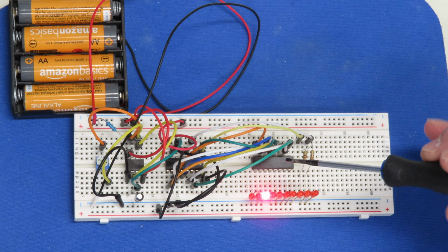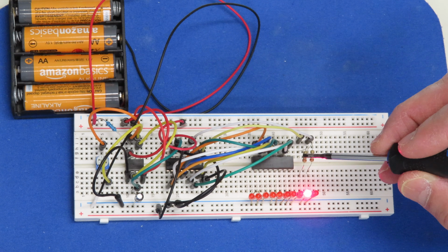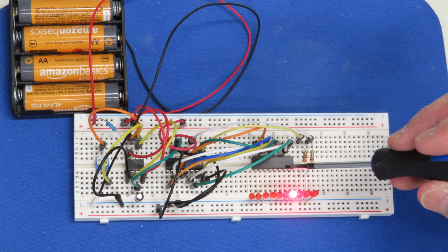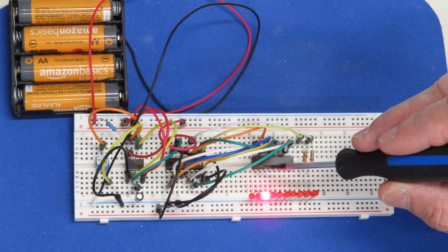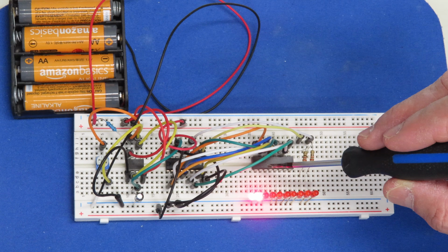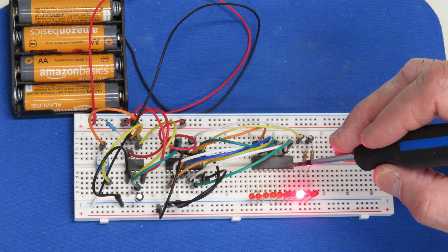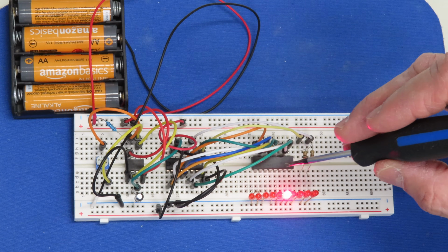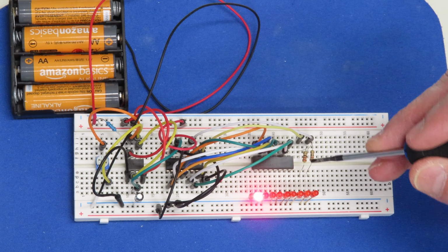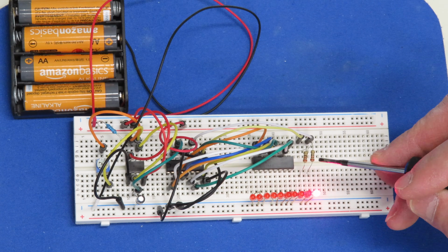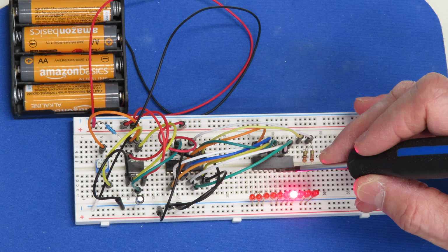This is not an integrated circuit. This is what's called a resistor array, and all it is is a series of resistors. Now, this is a 16-pin array, and it has 8 resistors in it, so it's got 8 220 ohm resistors, and there's one resistor connected from pin 1 to pin 16, another one from pin 2 to pin 15, etc., etc. And so this prevents me from having to wire up 8 independent resistors, and so it's a lot easier to wire and it's a lot simpler on board space. And of course, since I needed 10 of them, I've got 2 discrete 220 ohm resistors over here. But if you're building things like this, a resistor array is a very handy thing to have.